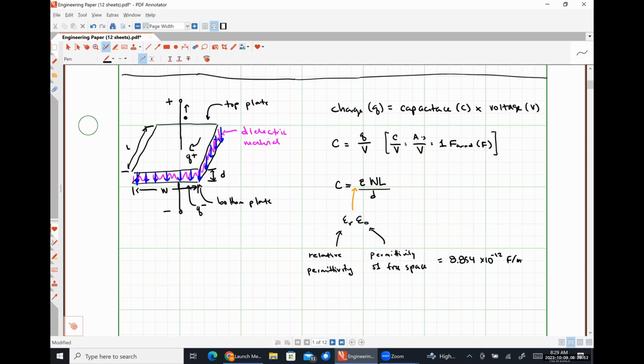The permittivity of air is only very, very slightly higher than vacuum, so the relative permittivity value there would be like 1.001 or something like that. So air and a vacuum are roughly the same permittivity. I'm just trying to explain to you what types of things impact the capacitance values that we're going to see. All right.